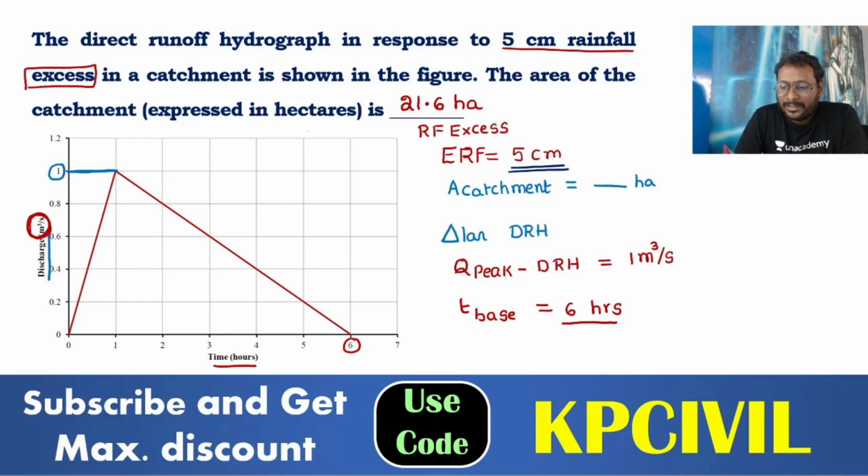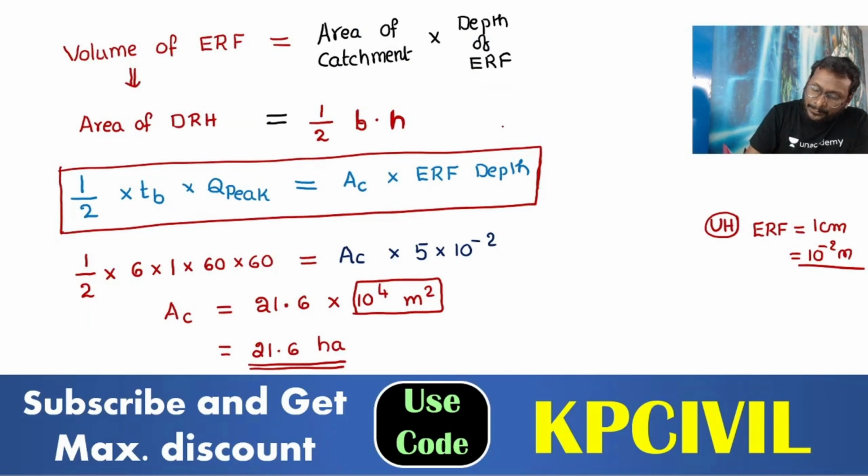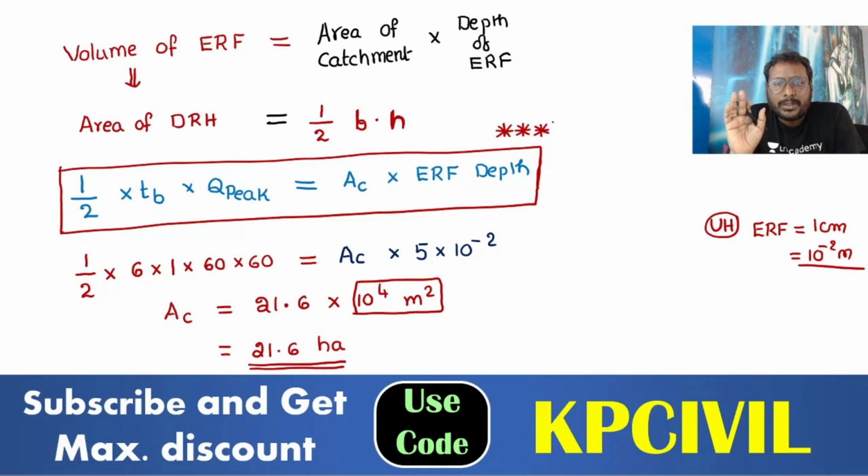Any difficulty? If you know the basic shortcut formula, half into time base into peak discharge is equal to area of catchment into effective rainfall depth, you can solve any triangular unit hydrograph or triangular direct runoff hydrograph questions. Any model, easily you can solve it. Simple. We'll go ahead now. First question, 2 marks, you got it.